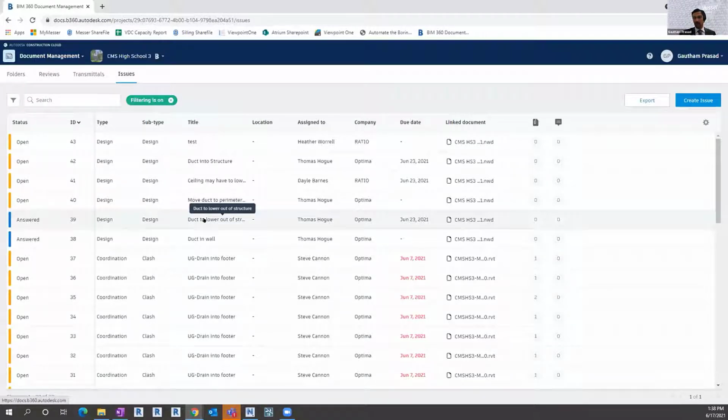We're hitting 15 or 20 in a meeting. And now we're going from Navisworks up to the cloud. Or I should clarify, we can create issues in Navisworks that push up, but if you run your clashes in Navis, you can't push your clashes up. That makes sense. I may have said that too quick earlier.